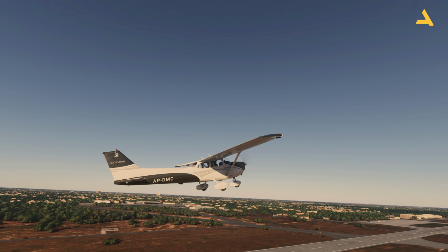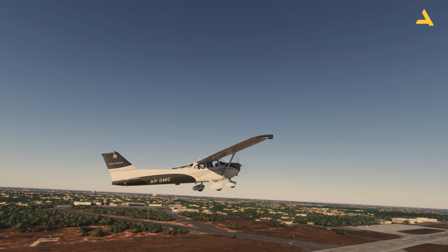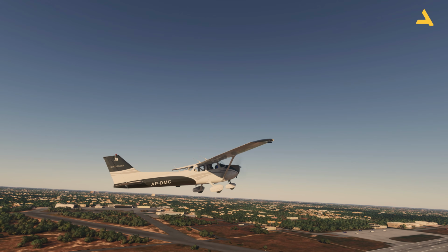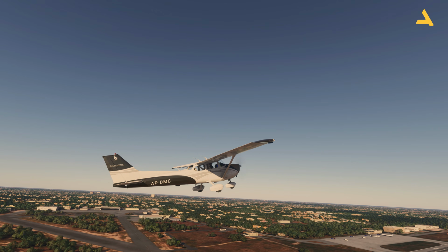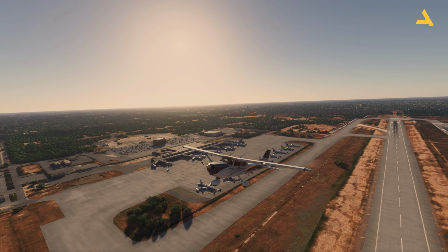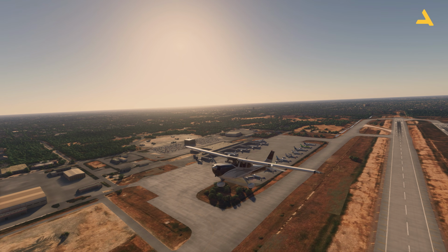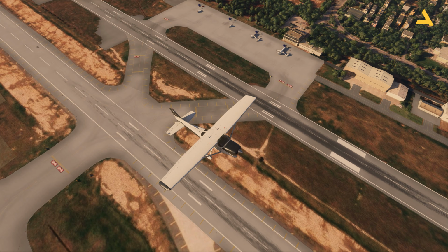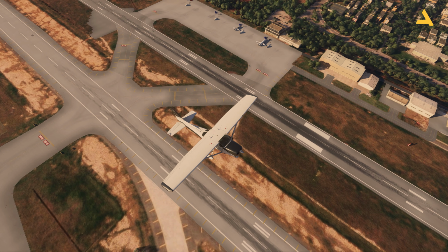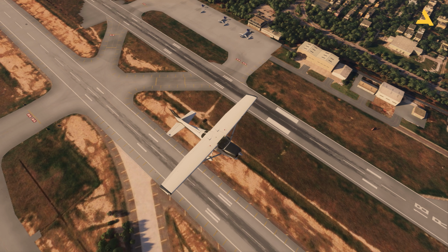If you know how to carry out VOR navigation, then you can just fly any plane without a proper flight plan made by SimBrief or maybe Skyvector or Little Nav Map. You can just select any VOR, fly your plane, and then you can carry out an ILS approach and landing if the plane has ILS approach and landing capability.